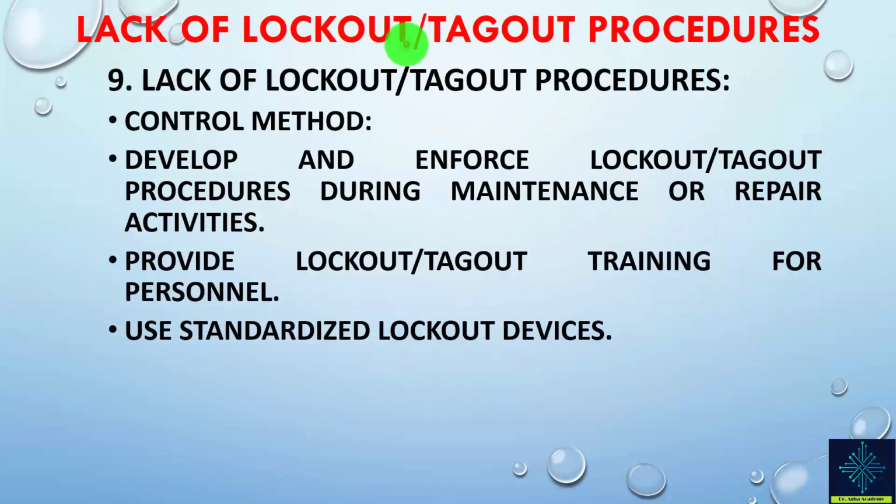Lack of lockout tagout procedures is again a source of hazard, sometimes also serious, and fatalities might take place, and fire might also arise because of this. So to control this hazard, we have to develop and enforce lockout tagout procedures during maintenance or repair activities.